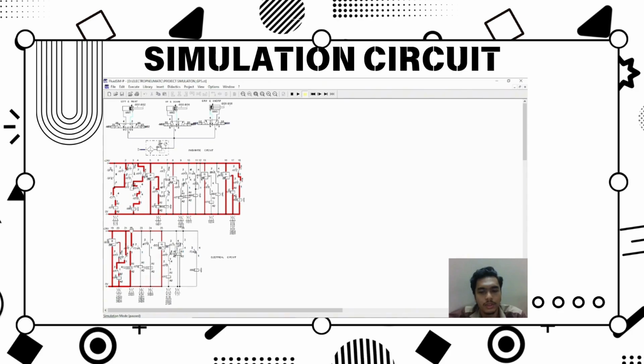Then magneto proximity -BG5 will close contact, and current flow will go through relay contact -KF5 and -KF7 in close contact to energize coil relay -KF6. And relay -KF6 will open and deactivate -MB5, which is here.